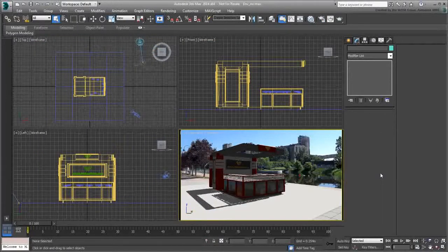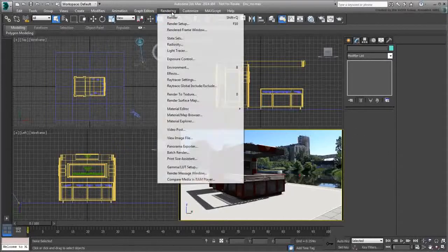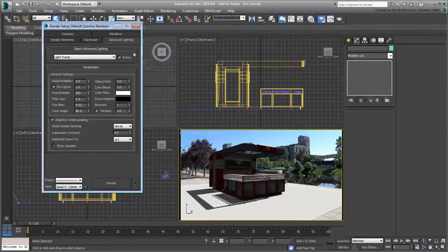Before you switch rendering engines, keep in mind that a few options you used earlier are not quite compatible with mental ray. The light tracer engine you used earlier, for example, is not compatible with mental ray at all. Another feature that is pseudo-compatible, but not meant to be used with mental ray, is the standard matte shadow material. To see how mental ray affects these two features, make sure you can see both the advanced lighting panel and the slate material editor.